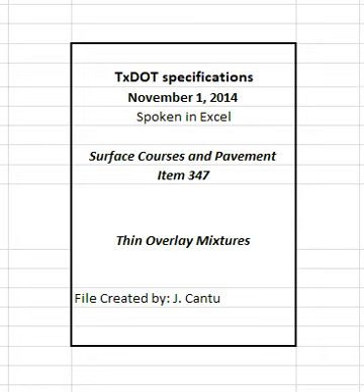4.4.2.2.9 Approval of JMF3 and subsequent JMF changes. JMF3 and subsequent JMF changes are approved if they meet the master grading limits shown in Table 6, mixture requirements shown in Table 7, and are within the operational tolerances of JMF2 shown in Table 8. 4.5 Production operations. Perform a new trial batch when the plant or plant location is changed. Take corrective action and receive approval to proceed after any production suspension for non-compliance to the specification.